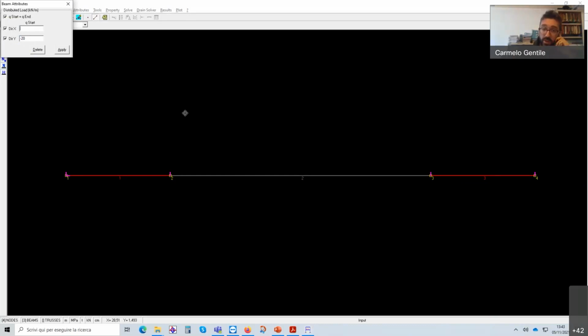According to the distribution of the loads, if we want to design this continuous beam with respect to the maximum bending moment in the midspan, we should know that if we load the first span more than the others, we will find higher bending moments here rather than if we load uniformly all the spans.